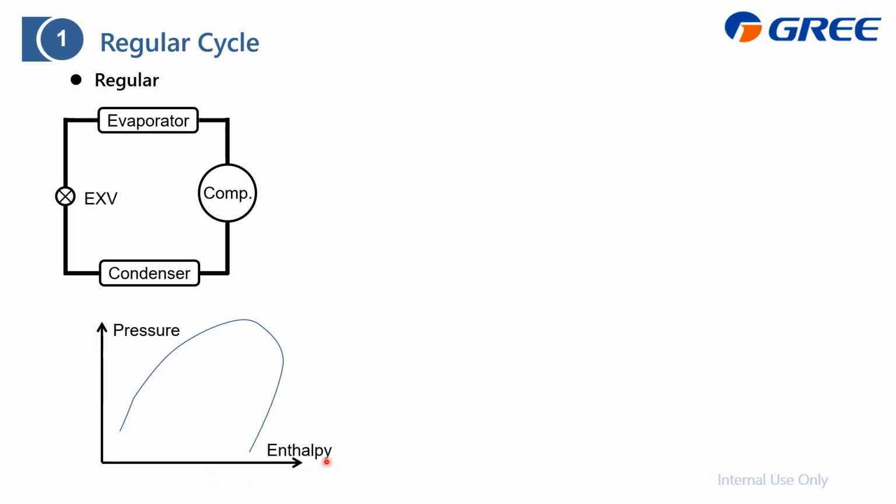So first of all, from the compressor, this one, we compress the low pressure vapor into the high pressure and temperature, go to this one, and send this vapor into the condenser, just like this, to release heat. Then this is still the high pressure. After that, it will go to this point. That means it has already become the liquid.